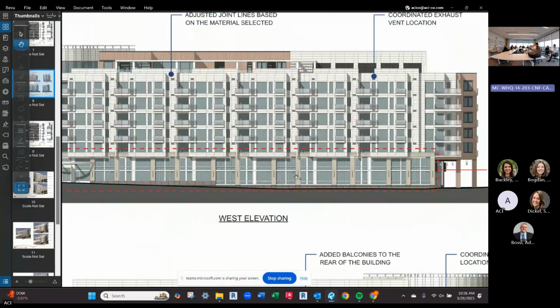On whether that's helpful or not helpful. I remember we had this conversation last time, and the reason for brick is that if you do a metal panel or EIFS, or cementitious panel, you cannot take those materials all the way to the ground for practical reasons. And granite is at the base because you have a ton of bioretention planters, for practicality. How are you going to maintain it? It's not brick. Brick is too porous, right?